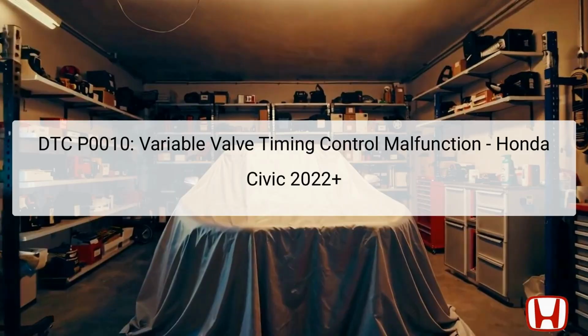DTC P0010 indicates a malfunction within the Variable Valve Timing Control (VTC) Oil Control Solenoid Valve A. The VTC system is critical for optimizing engine performance and efficiency by adjusting the timing of the intake valves, thus improving power output and fuel economy. The oil control solenoid directly controls the amount of oil supplied to the VTC system, affecting the valve position.